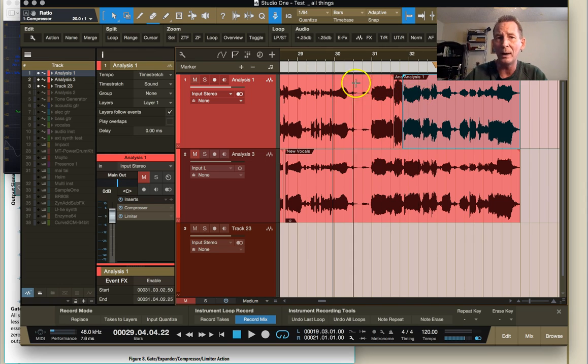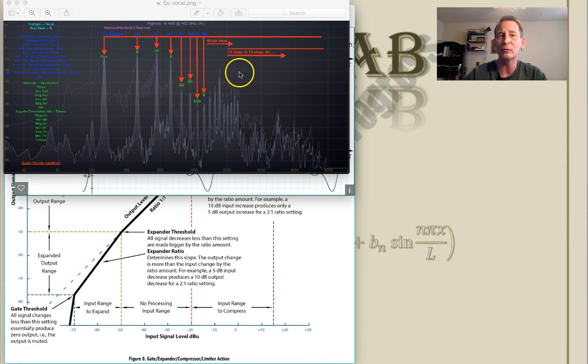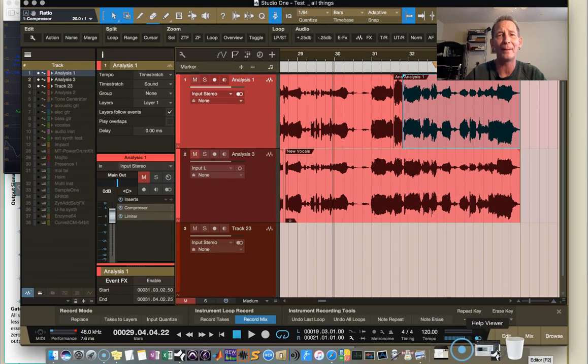Now, the other way to look at that is you're trying to reduce the dynamic range of the spectrum. So for that one section we're looking at, you are trying to reduce the dynamic range between these higher parts and these lower parts, trying to compress them together. And you're going to push the noise floor up, and you're going to push noise up from the noise floor. So that can be happening also. That's a whole other application.